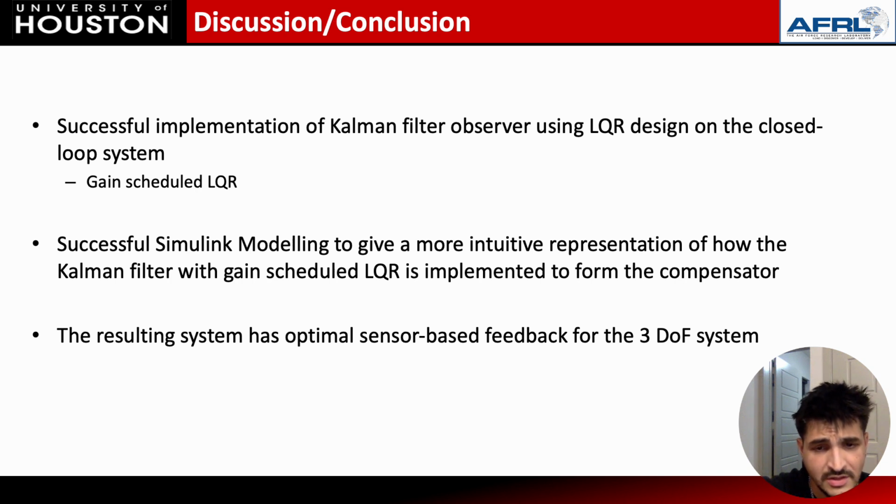So that way the systems can be designed individually, but then operate together to form the compensator for filtering out the noise. We show successful Simulink modeling to give more of an intuitive representation of how the Kalman filter with the gain scheduling is implemented, and how the resulting system has optimal sensor-based feedback for the 3 degree of freedom airfoil.